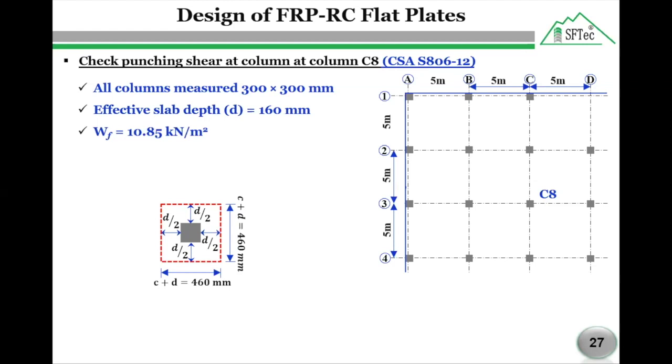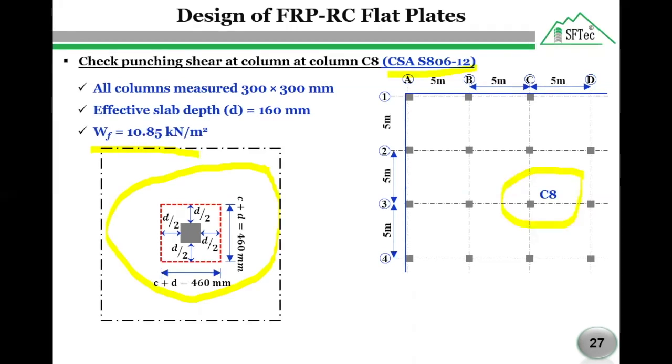So we need now to find the tributary area. That is the force pushing down that is going to separate the critical shear area from the rest of the slab. Okay, let's draw it. What is this area here? The dimension is simply half the length between columns.